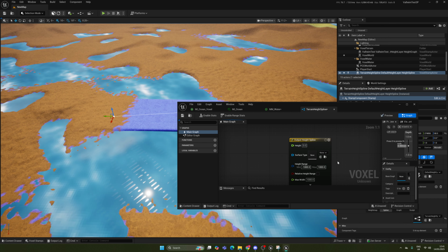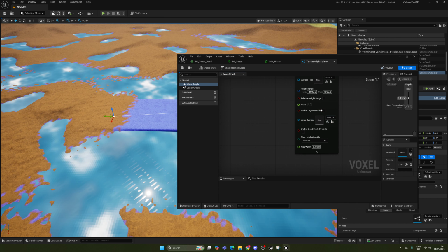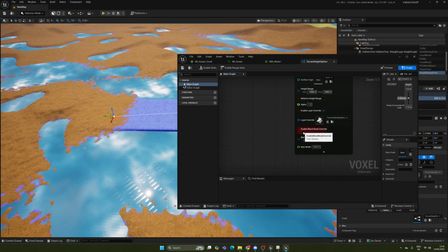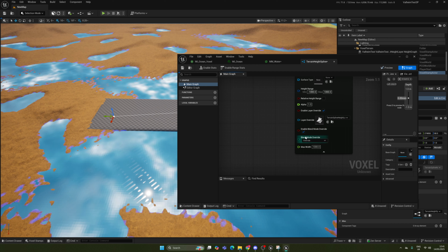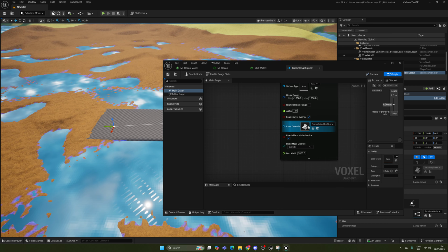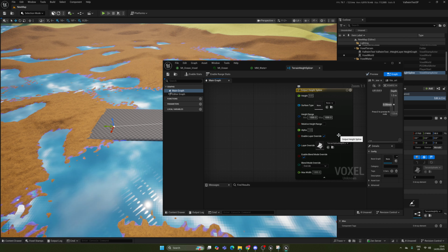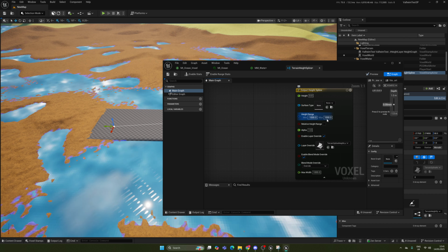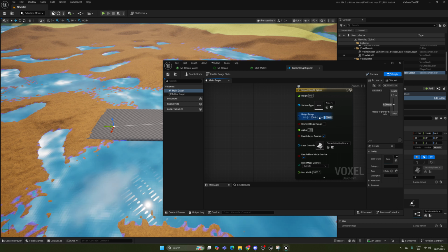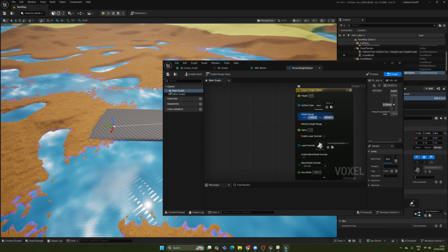But the first thing I'm going to do is override the spawning layer. I want it to affect the terrain spline layer, and I also want it to be set to override. Okay, so now it's not doing much of anything useful, but we can go ahead and make a change. Because this is affecting the terrain, the height range is going to be roughly the maximum or minimum height of our terrain. So I'm going to change it to 30,000 on each of these for now.